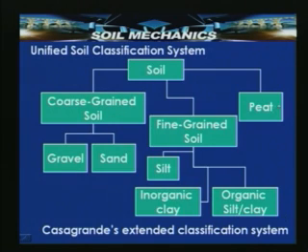The third one is peat, which covers peaty soils or muck type of soils, if the soil exists at the particular site. We have discussed that peat soils are highly fibrous soils, which are required to be replaced or to resort to a ground improvement technique.